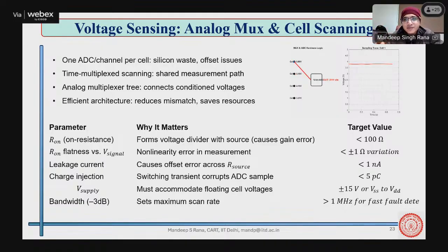So they would put ADCs which sample something from 10 to 12 inputs. That's usually the order at present. ADCs will become faster with time, and we will be able to sample more and more data through one ADC, but at present the standard is 10 to 12. Now, when we do multiplexing, there is a lot of noise coming from, let's say, the filter side.